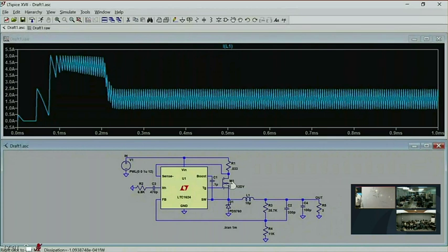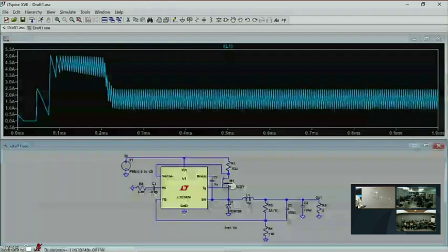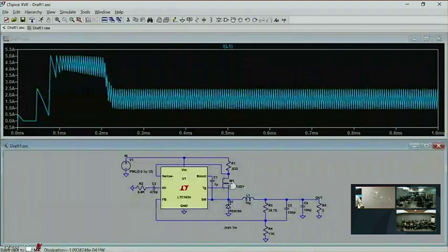And the voltage buffer is the lowest frequency part of the whole op amp. So if I just don't print these output buffers, I get a part that works better, and I print fewer transistors. It's all win-win. So I only use transconductance amps. The output is a current, and I read out the current with a compensation network to a voltage.